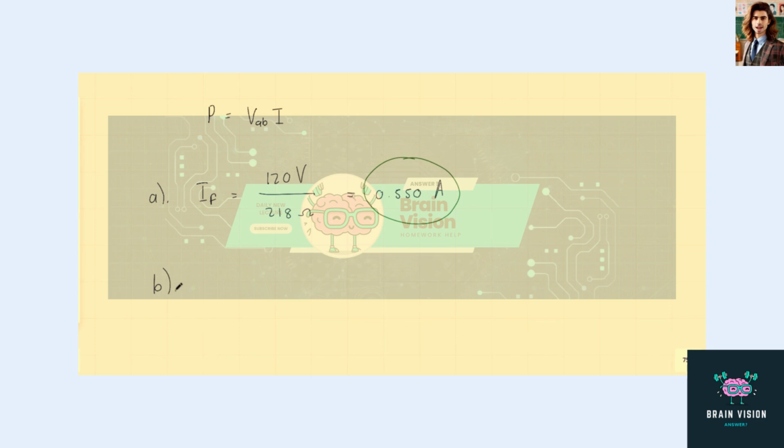In part B, we want to calculate the rotor current. So the rotor current, IR, is equal to the total current minus the field current.